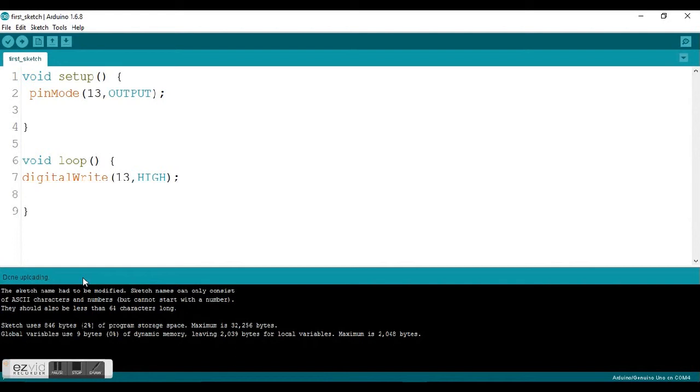The first sketch that any Arduino user ever does is the blink sketch. So what we're going to do is set this up so that it blinks. We need to break down that process into very specific, deliberate steps. So I'm going to start by using some pseudocode with some comments. My first line, of course, is to turn on the LED. We've already done that. What we want to do for a blink is turn it on for a short period of time. Let's say 1 second.